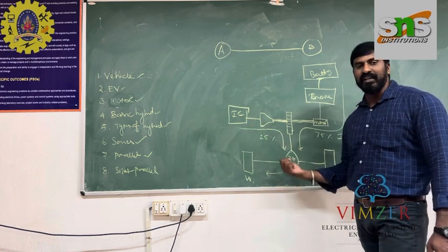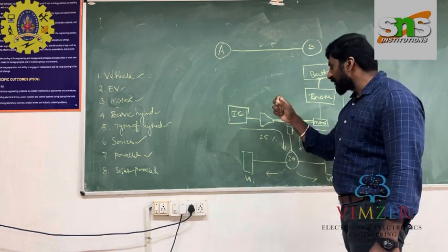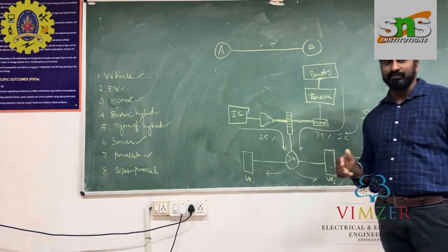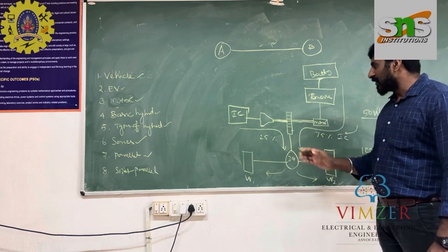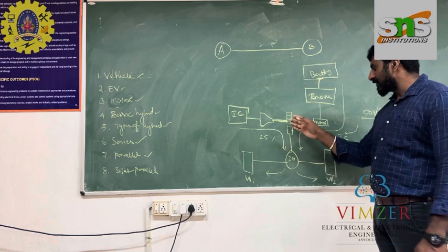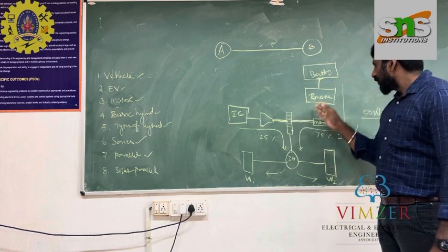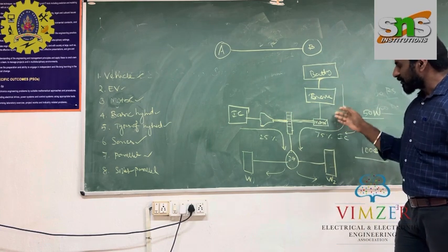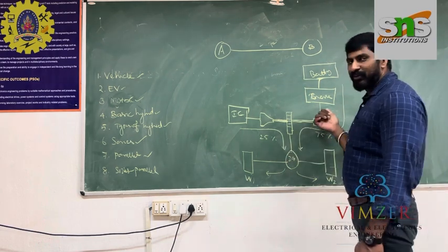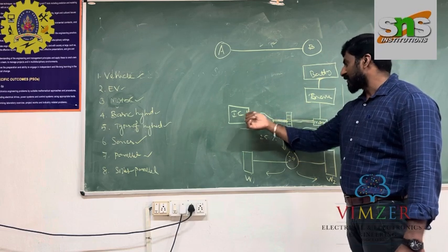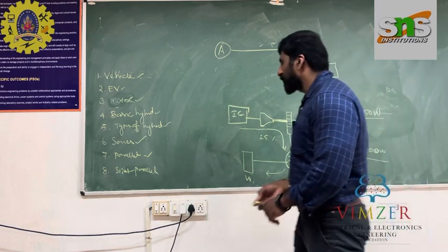The internal combustion engine delivers 25% of the power. This power is taken from the internal combustion engine through the gearing arrangements and gearing mechanism. This gearing mechanism has two different kinds of sources. For example, if we do not need the internal combustion engine, the gearing mechanism can easily cut off the engine input, and the vehicle is driven only by the battery, inverter, and motor. If the battery power goes to 0, at that time we can run by the internal combustion engine and gearing to the wheels. So this is called a parallel hybrid system.